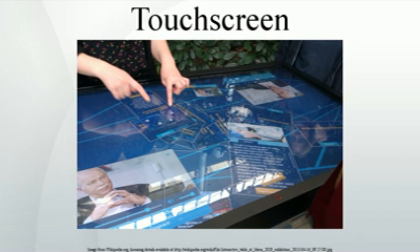It can be overcome with a special capacitive stylus, or a special application glove with an embroidered patch of conductive thread passing through it and contacting the user's fingertip. The largest capacitive display manufacturers continue to develop thinner and more accurate touch screens, with touchscreens for mobile devices now being produced with in-cell technology that eliminates a layer, such as Samsung's Super AMOLED screens, by building the capacitors inside the display itself.